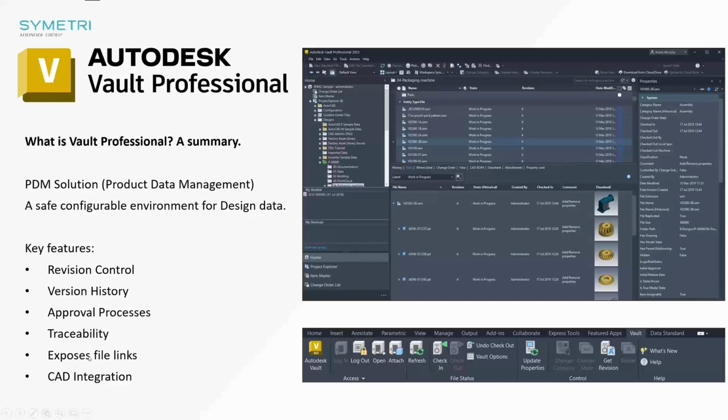Anyhow, as I was saying about exposing file links, we just have an Inventor assembly here, top level, and you can see all of the parts that make up that assembly in the screenshot. So this is something you can do with Autodesk Vault. This works for XREF AutoCAD drawings as well. You can look at a top level drawing and see all of the drawings that are XREF'd into that file, or like an Inventor assembly, you can see all of the parts that are used in making up that assembly, even if those parts are in different folders.